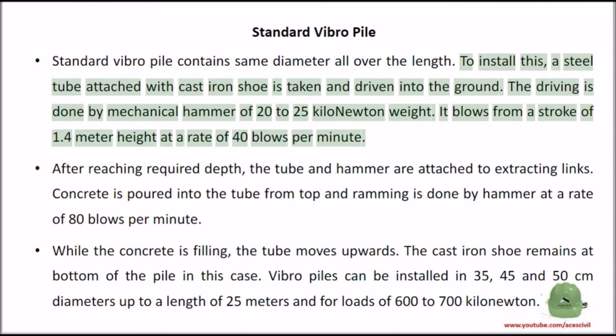To install this, a steel tube attached with a cast iron shoe is taken and driven into the ground. The driving is done by a mechanical hammer of 20 to 25 kN weight. It blows from a stroke of 1.4 meter height at a rate of 40 blows per minute.